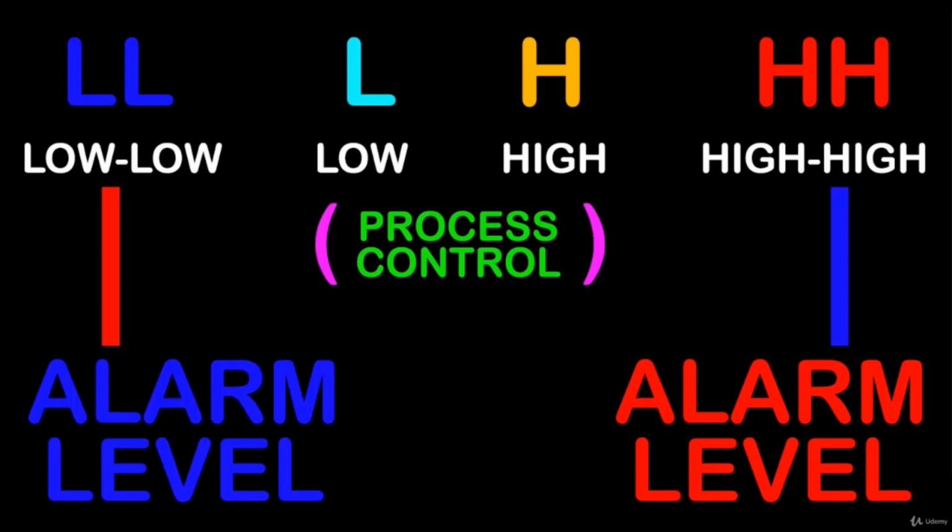But sometimes things go wrong. Perhaps our heater broke. Perhaps a wire fell off. In which case, our logic is telling the heater to run. And as far as our logic knows, it can't tell that the heater is broken. All it knows is it's energizing the output to the heater, and it should be running.